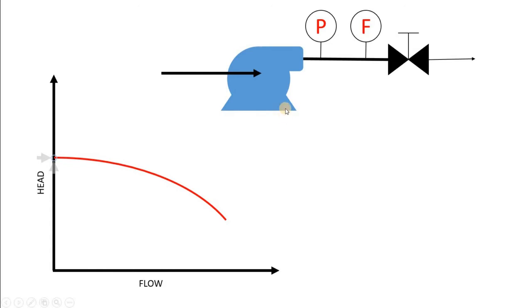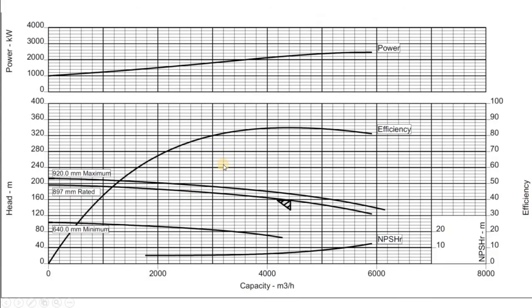This is a typical pump, one pump, fixed speed. This is the pump curve. This valve represents the system load. So when you open it or close it, it is as if the system itself is moving along the pump curve, on the system curve, which will be here. When you buy a pump, they will give you this flow chart for the pump, capacity versus head. Of course, there are a lot of things here: you have the power consumption, the pump efficiencies, the NPSH, and different pump impellers. The design point is here. So we would buy this pump with this characteristic.